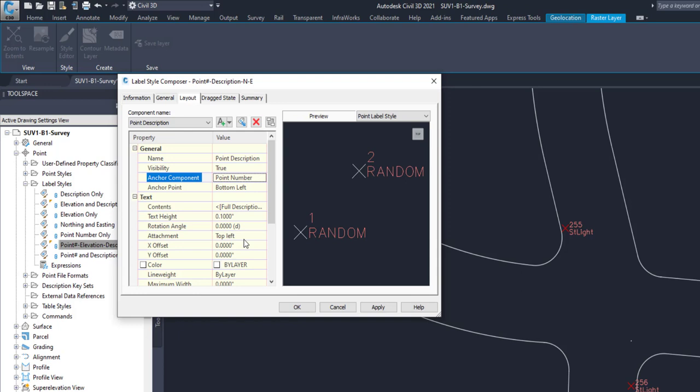With those options selected, I'm going to go to the Create Text Component option. I'm going to click on the text component, and change the name. The default is, of course, text 1. I'm going to change that to coordinates.